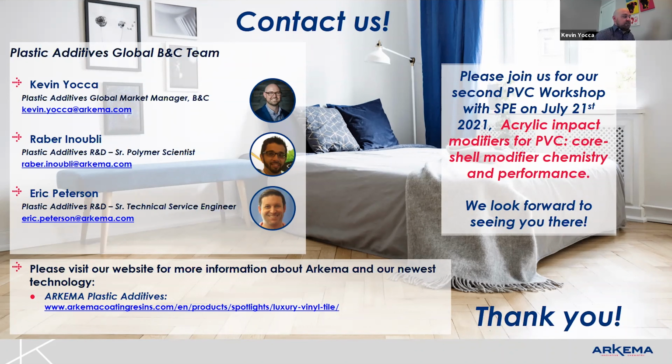I know I've seen as high as 17% for the crystallinity, but really you're talking about a minimum amount. So this isn't like PLA where you can actually use the crystallinity to drive the mechanical properties to a totally different level. It's a minimum amount, but that minimum amount is what you're trying to reorder when you do the correct amount of gelation and get the mechanical properties. So I think maybe 8 to 10% is kind of a happy high range for what you would see.